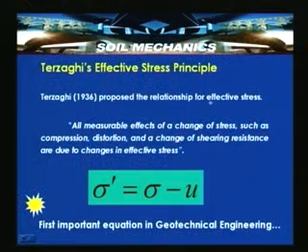Now, having introduced the total stress and the pore water pressure, we have come to an important milestone in our lectures: the concept of effective stress, or Terzaghi's effective stress principle. It is very famous, particularly in geotechnical engineering, where it gives the apportioning of the load carried by the mineral grains and the pore water pressure. Terzaghi, in 1936, proposed a relationship for the effective stress.